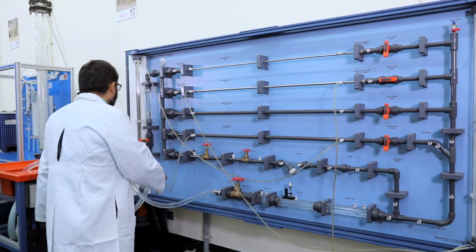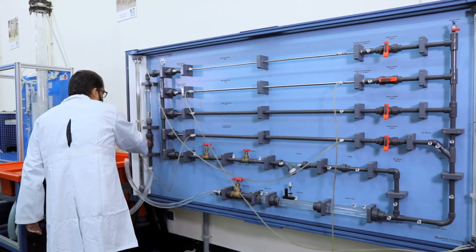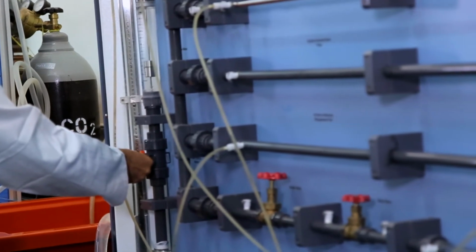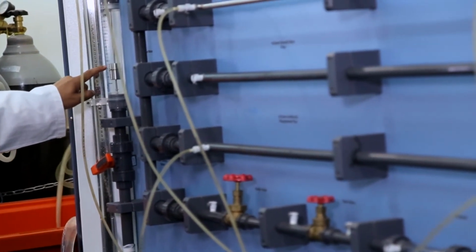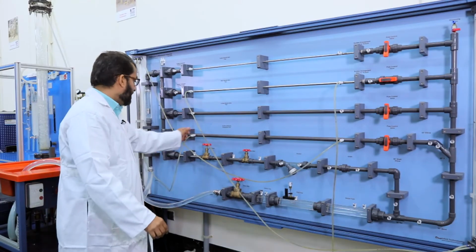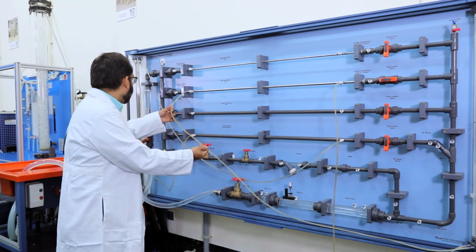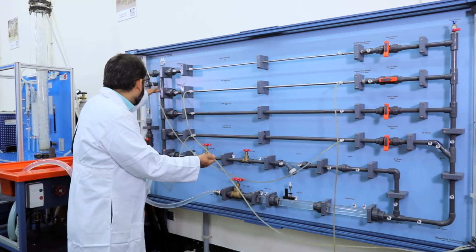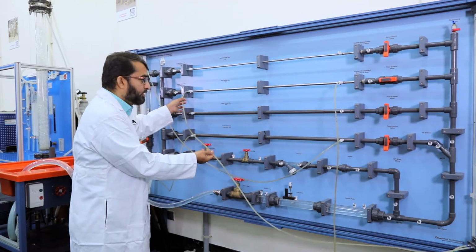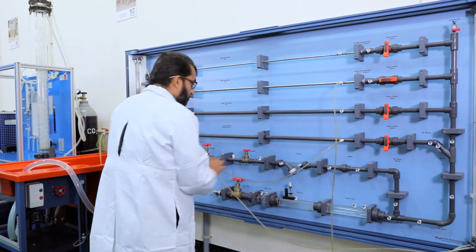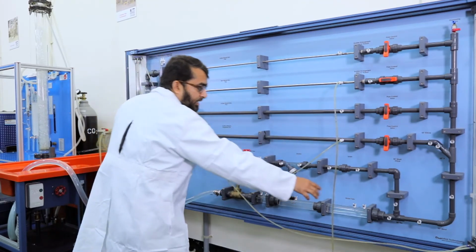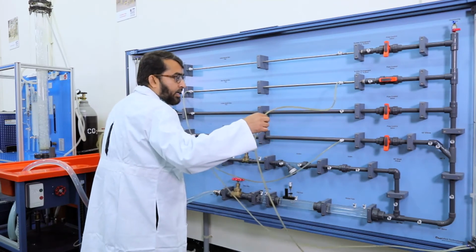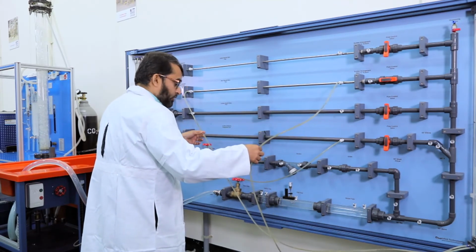Okay, so now I can open the valve a little bit, and you can read the flow rate using this flow meter. Now you see this one is P1. Water is flowing like this. So this is P1, this is P2. What we expect is that P1 will rise to rho g H1, and this one to H2.